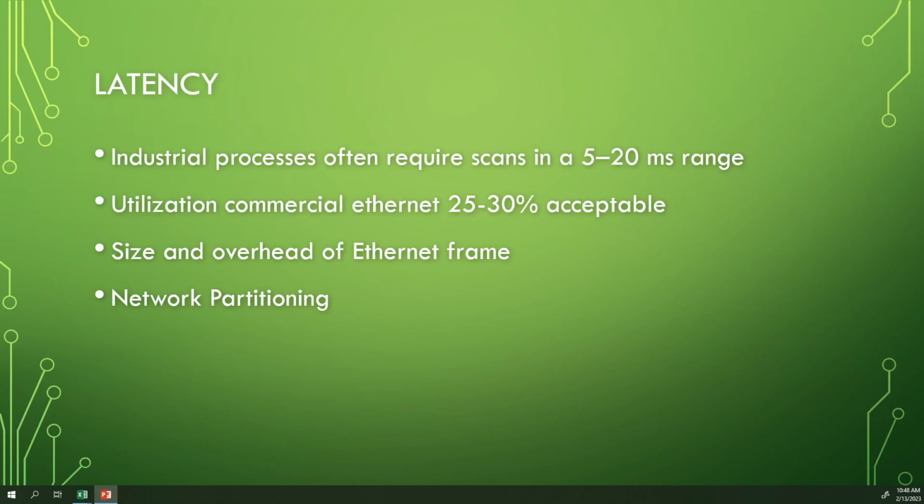If we say fill till the tank is full, and we don't get that signal for 2 seconds or whatever, there's now an extra gallon or 2 of liquid in there, and that completely screws up the ratio. Maybe shampoo is not a big deal, but with something like cookie dough, now the flavor is going to be different. There is a need for low latency for certain things. My notes say that for really demanding processes, that could even be down to 2 to 5 milliseconds.